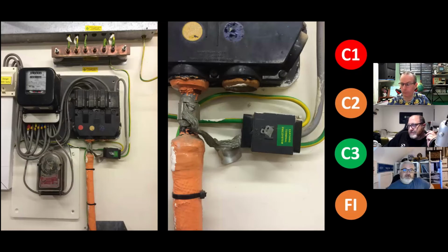The fact of the matter is we're now entering that world where we can guarantee a live conductor into each installation, but we can't guarantee a neutral and earth connection. Now maybe people will start to realize why foundation electrodes are coming into the regs, because all that's happening is it's being kicked over the fence to the consumer and to the contractor. Yeah, and you put a foundation electrode in, you've got your own neutral earth reference point. And fundamentally, if we do go down that avenue of foundation earth electrodes and then islanding, we are going to get rid of a lot of these problems. Yeah, we will.